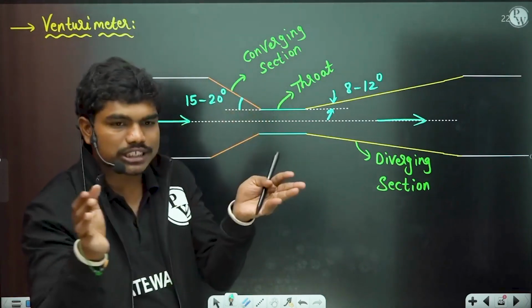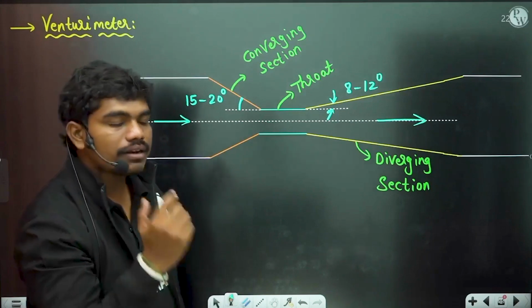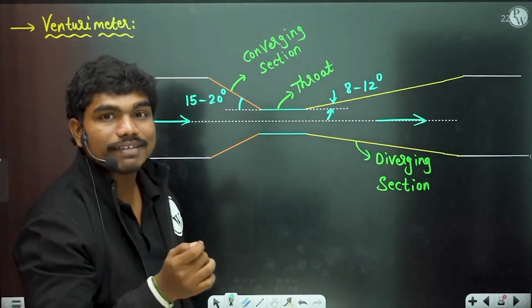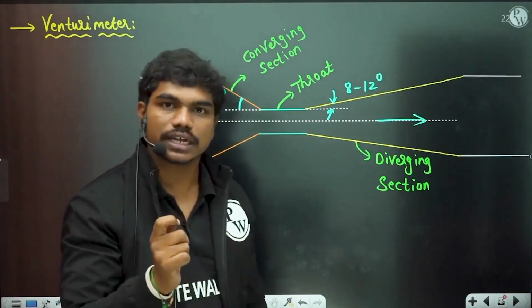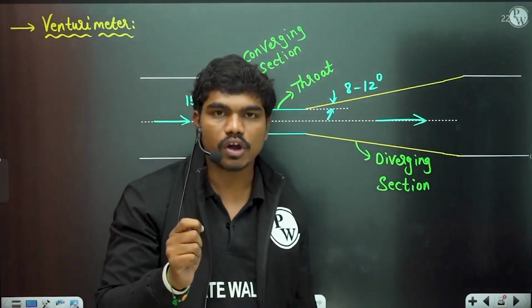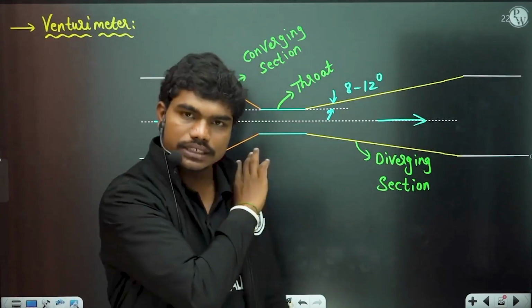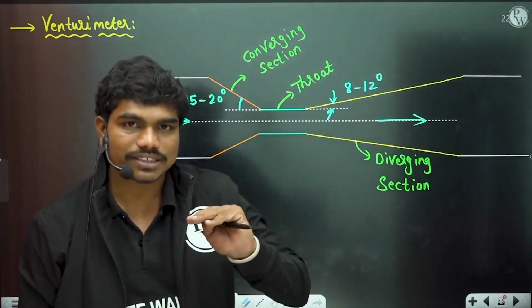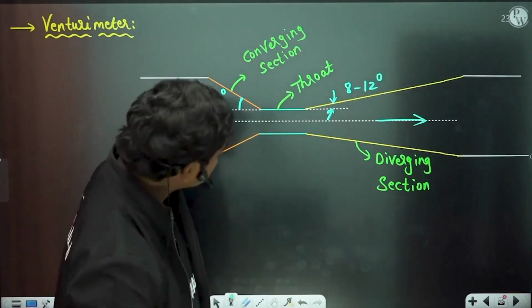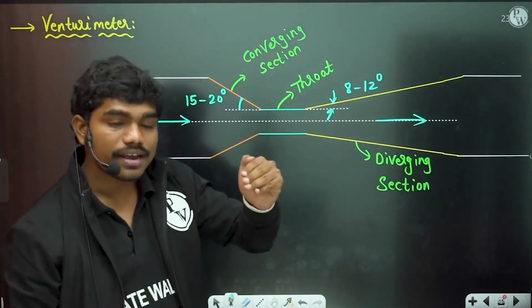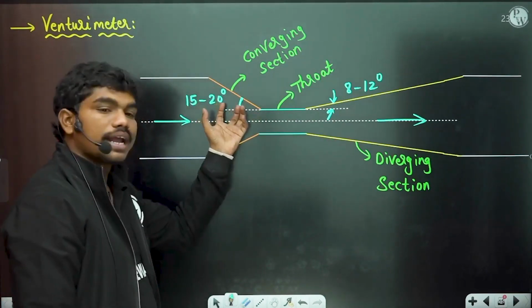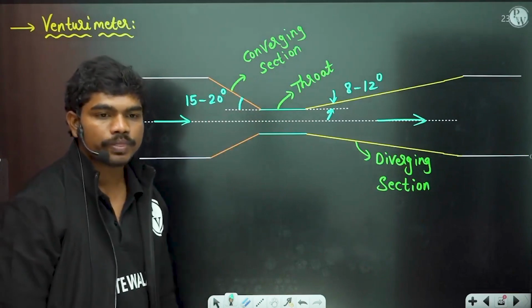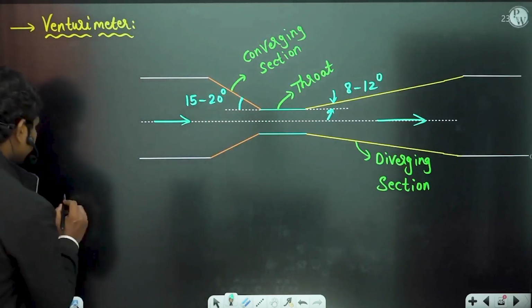Whenever the cross section decreases very fast, you have something called convective acceleration, which you have studied in fluid flows. You remember this? There's something called convective acceleration. Of course, things are steady, nothing is changing with time, but in the case of convective acceleration, definitely the convective acceleration term will be high when you connect this higher cone angle in the upstream direction. Yes or no? Can you understand this?